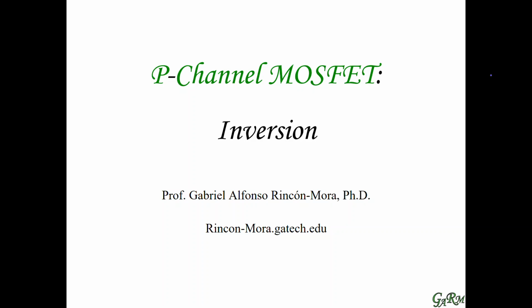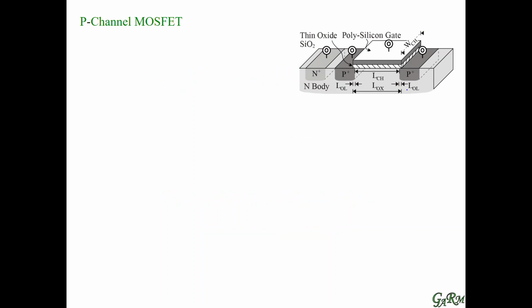This video is on the P-channel MOSFET, and more specifically on inversion. Structurally, what we have here is a P plus diffusion on one side and another P plus diffusion on the other, and between them is where we want to have a channel eventually.